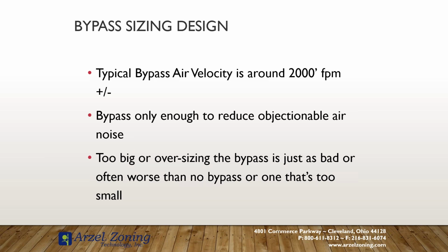And this is bypass design only. This is not standard duct design. This is bypass duct only. And we want to size it to reduce the objectionable airflow noise because too big of a bypass is going to be bad for the equipment. And oftentimes it's worse than if you had no bypass at all.